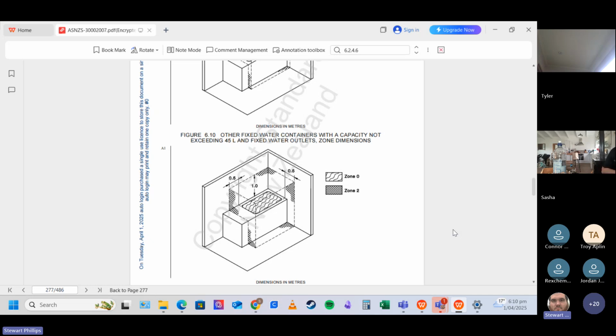But I also like to run laundries with a fan that's wired with a current sensing relay. So basically, it's a relay that as soon as you turn something on, it senses the current that then switches on the fan in the laundry. You'll see it a lot in large housing developments. As soon as you turn the washing machine or the dryer on, it clicks the fan on, and then it's got a run on of, I don't know, 5 minutes just to get rid of all the moisture in the air.